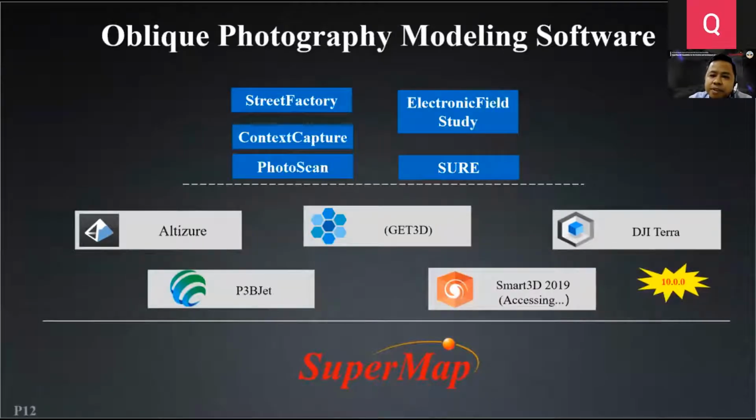These are oblique photography modeling software applications. Each of these software has its own data format. So how do we connect to these data formats and integrate them in the GIS platform? SuperMap provides a convenient and efficient model loading method by using a configuration file, mostly an XML file, to describe what data needs to be loaded. And then the original model data is called OSGB, as already mentioned, which is a common file format that most 3D modeling software is capable of exporting.